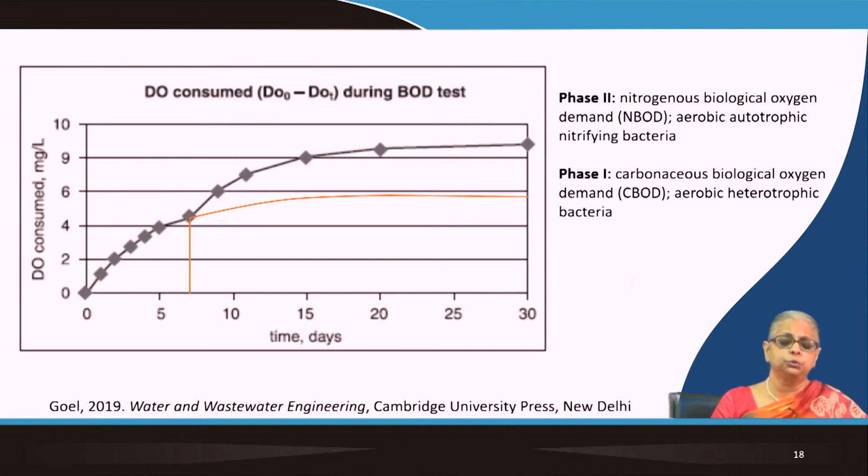If you were to do that, you would get a curve that has this shape. Okay, now what we are doing in a BOD test is just 5 days. That's a standard BOD test. You can see there is a slight inflection in the curve at about 7 days. I'm not teaching you all of these, but you can always refer to any textbook about water pollution.